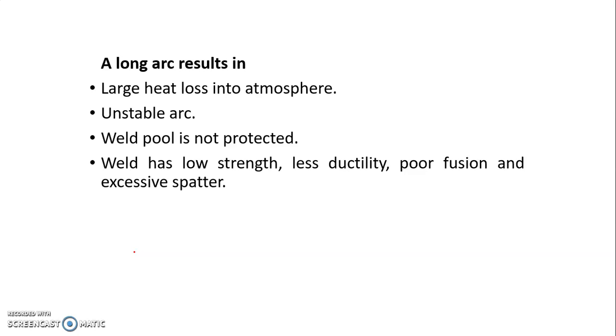Because of this, the weld gets contaminated due to the absorption of oxygen and nitrogen. Weld has low strength, less ductility, which is due to high porosity, poor fusion, and excessive spatter. These are due to the high porosity.